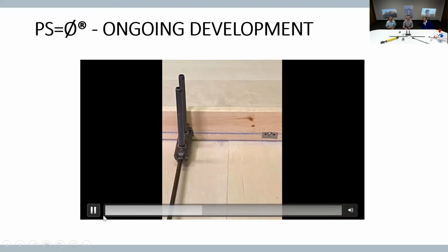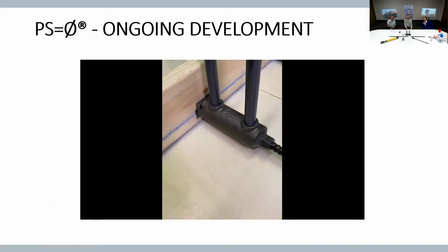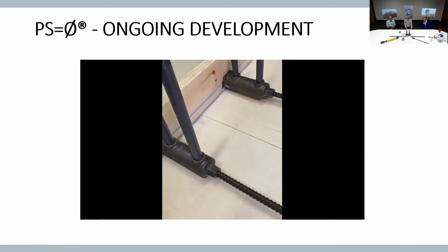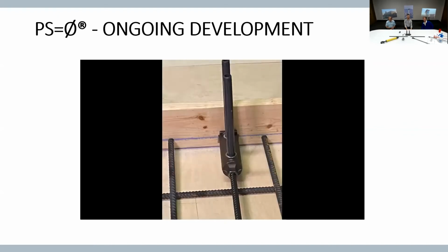And for the threaded couplers, we've gone to plastic pipes now because the contractors have found they'd rather cut them off than try to grease them and remove them. That's a little tricky process, to get them at the right time. And you can see the screws in the ears on the back of the coupler, so they can just screw them into the form, positioned by that form placer. And now we don't really need the boards on top anymore to hold those.